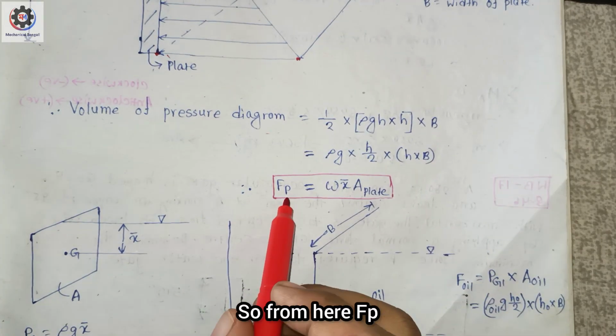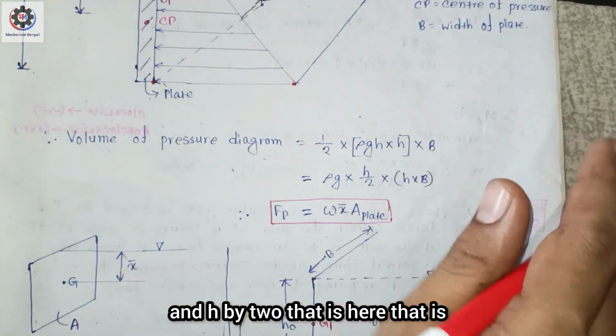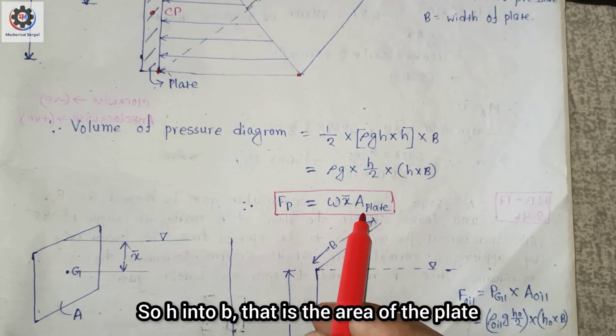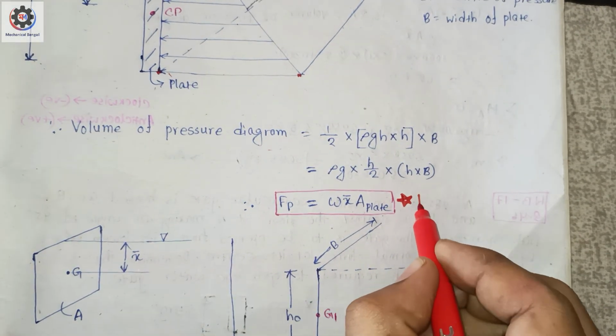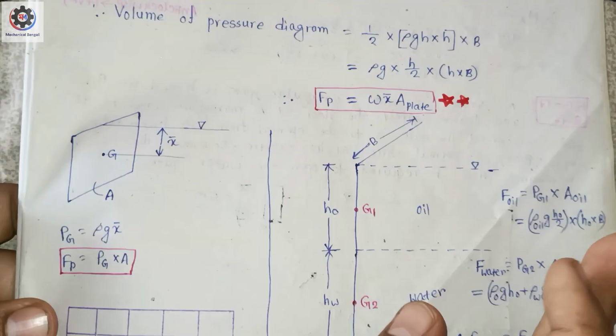So from here, Fp, the pressure force: rho g we know is equal to omega, and h by 2 is x bar. So x bar into the area of the plate, h into b, is the area of the plate. This is very important. Here Fp is equal to omega x bar into the area of the plate. Okay, this is very important.